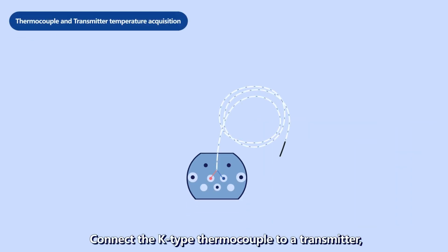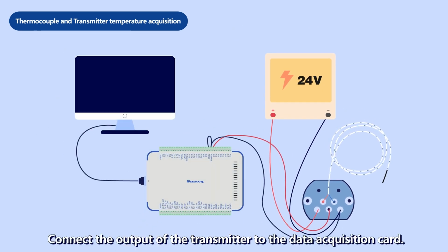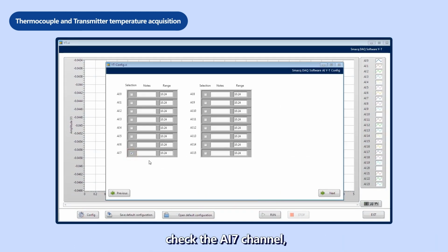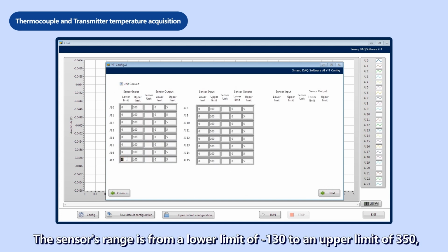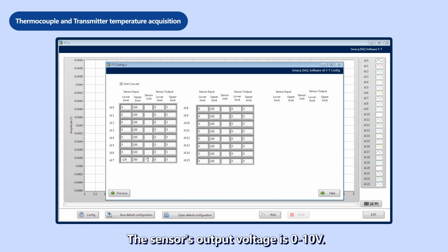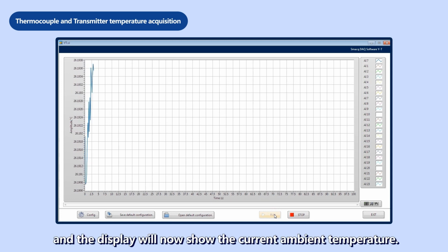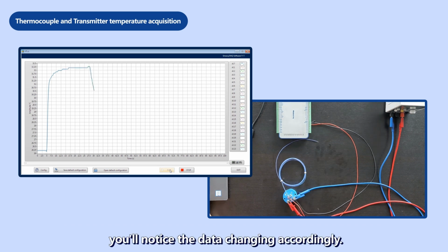Connect the K-type thermocouple to a transmitter, which requires power supply. Connect the output of the transmitter to the data acquisition card. In the software, set the relevant parameters, check the AI7 channel, and set the sampling rate to 5. Activate the unit conversion feature. The sensor's range is from a lower limit of 130 to an upper limit of 350, measuring in degrees Celsius, and the sensor's output voltage is from 0 to 10 volts. Other settings remain unchanged. Start data collection, and the display will now show the current ambient temperature. If you increase the ambient temperature, you'll notice the data changing accordingly.